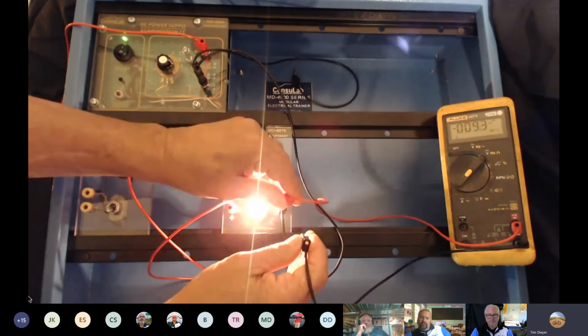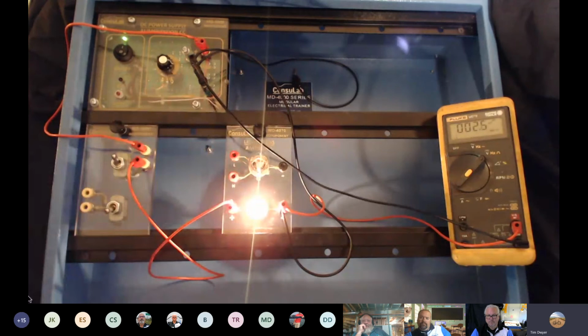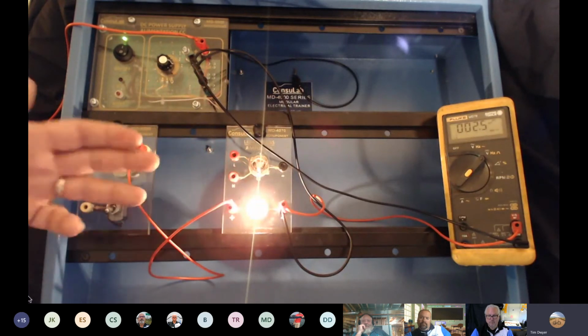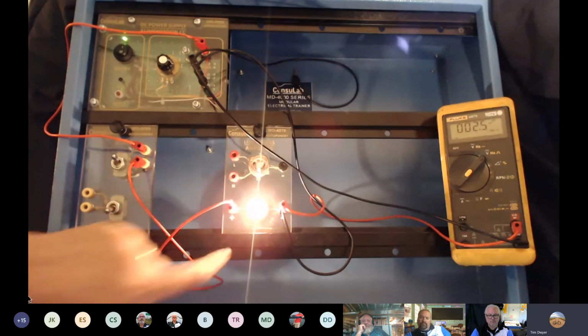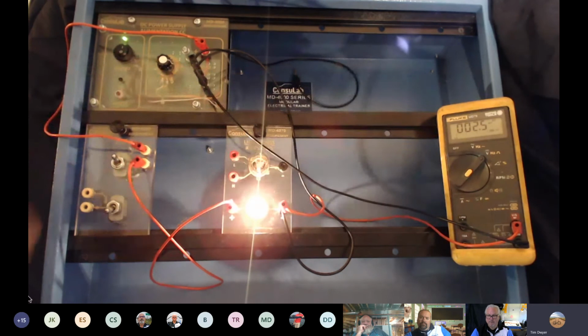Now I'm going to turn around and go positive to here and go to the battery and check the ground. And I'm happy with that whole circuit. In all honesty, there wouldn't have been a customer complaint. It's working as designed. The engineer wanted most of the voltage drop right here, and we verified it by proving it right there. Now I can go to a service advisor and say there isn't anything wrong with this particular circuit. Customer might have a complaint, but it's working fine right now.